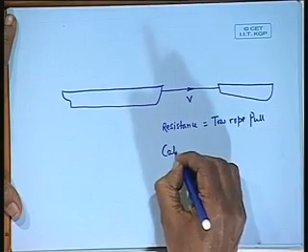Now, in a seaway there are of course a lot of disturbances such as air, waves, current, etc. Normally the tow rope pull is determined in calm sea condition without any disturbances other than the resistance to motion due to movement of water and some amount of air resistance. So, sometimes this is also called the calm water resistance.